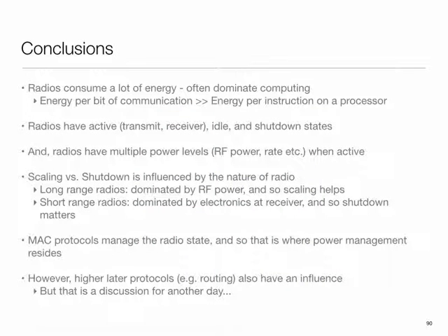So the main conclusions out of this are the following. Radios are a big energy consumer in the tinier devices, even for cell phone type stuff. Normally our protocols were designed for transmission being the bottleneck, but since reception is often the bottleneck, we are trying to optimize for that.